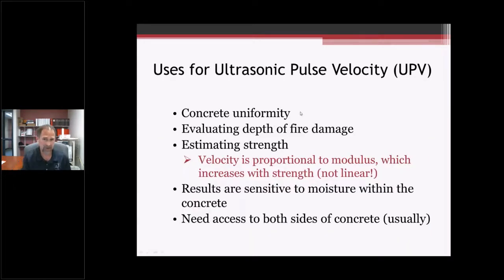So what can we use ultrasonic pulse velocity for? Like I said, concrete uniformity, finding voids, unconsolidated concrete, maybe poor concrete, evaluating the depth of fire damage. I'll talk about that in a minute. Estimating strength, we'll talk about that towards the end also.